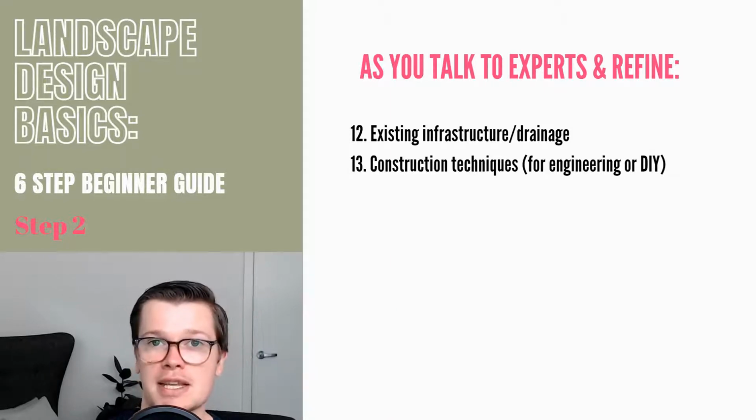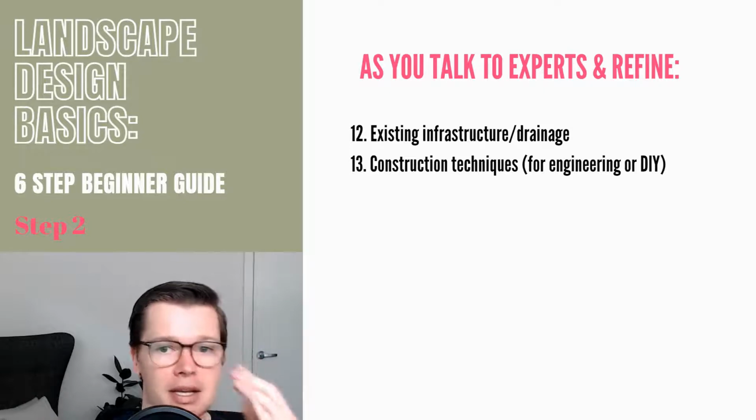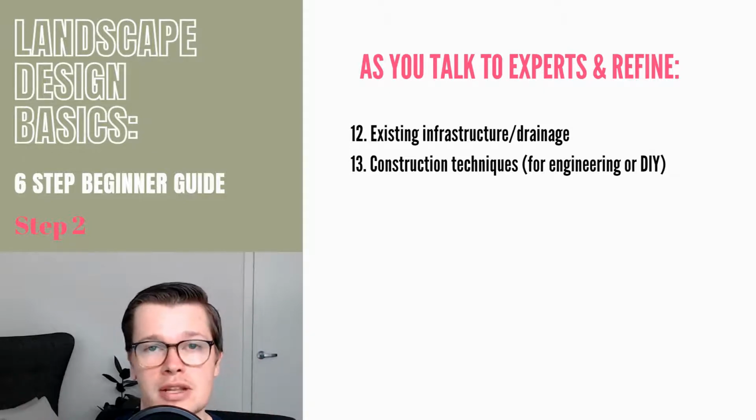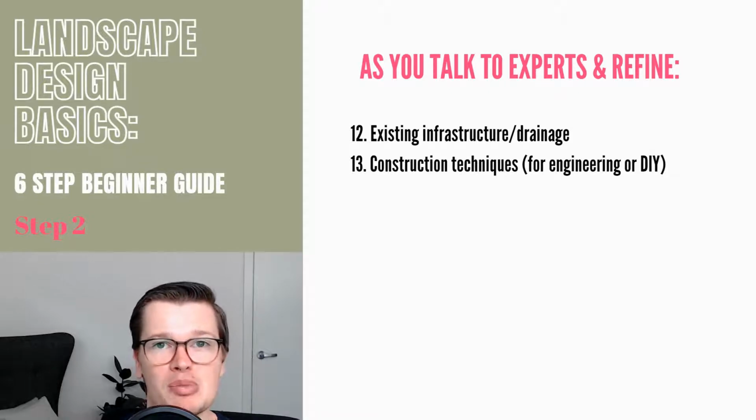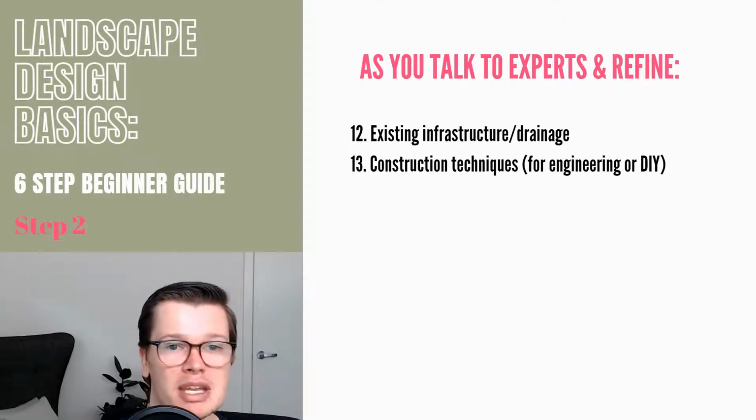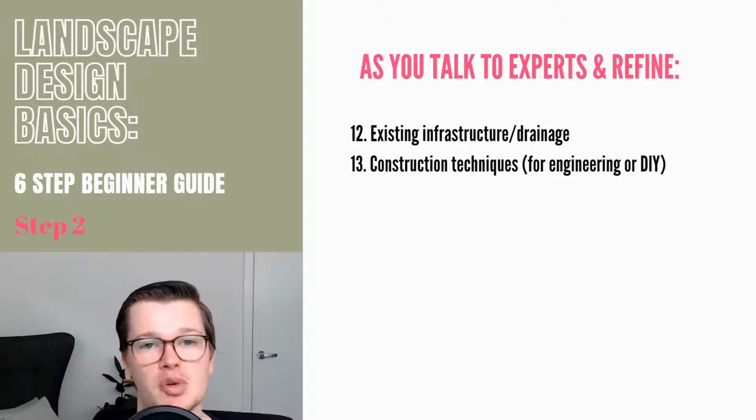Again, construction techniques are another thing, whether you need it for engineering, so that's going to be a lot more expensive, but maybe you have a retaining wall that's greater than 1 meter, or I guess 3 feet in height. Generally, if that's the case, you need engineering in order to get a building permit, which you need to actually build it. So that's a bit beyond what you need to know right from the beginning, right? But knowing construction techniques or doing the research as you go can be really, really useful.